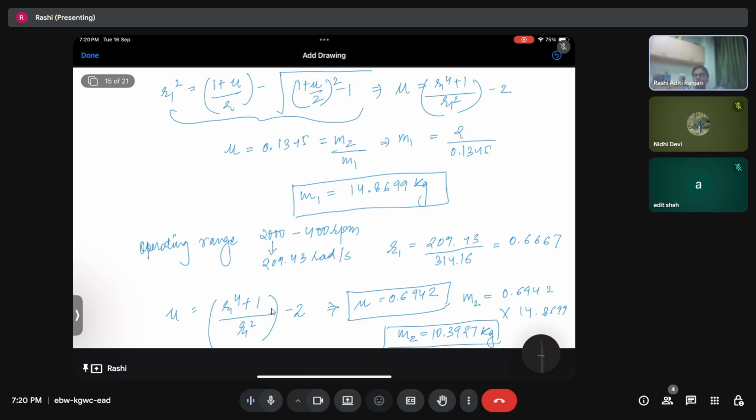I have taken 2000 as the value. It means I've taken it in a way that at 2000 I'm going to have a resonance. Whenever we are solving this kind of question, we are using some limiting values. But for a practical case, we should always take it less than 2000, so that even when my system is operating at 2000, it does not encounter resonance.